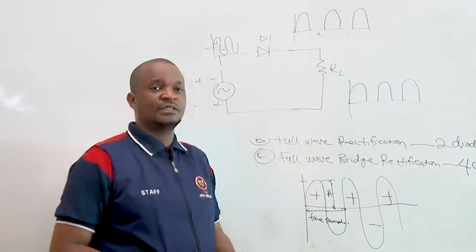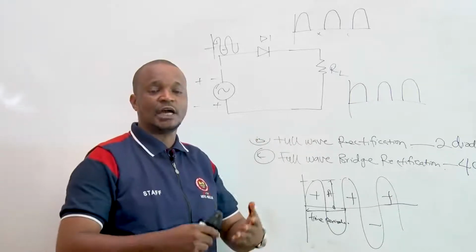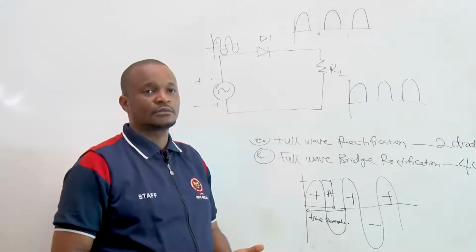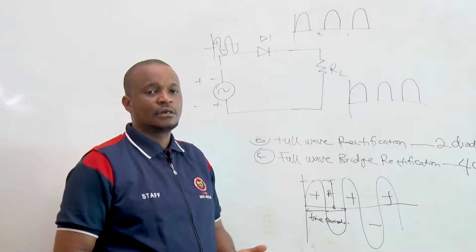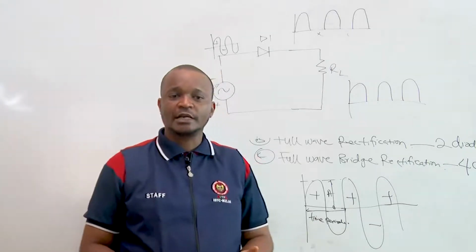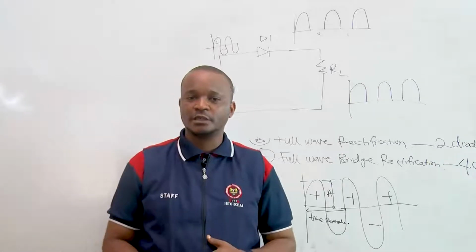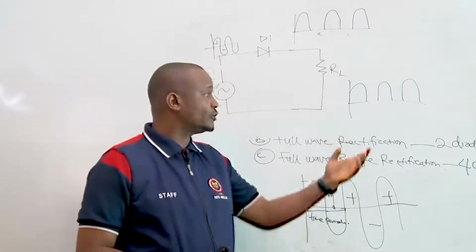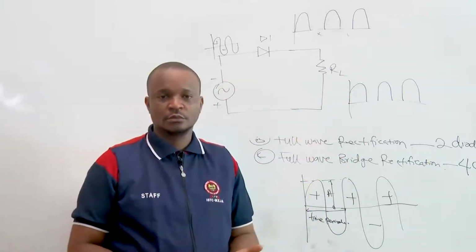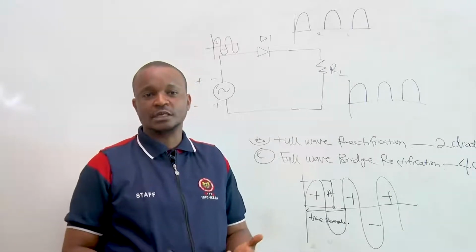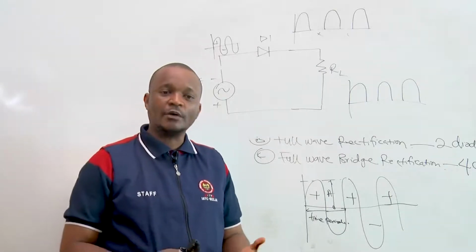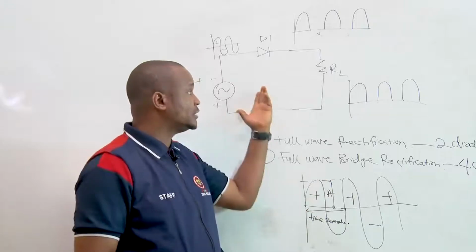However, there is a disadvantage to this. The disadvantage is that the output is difficult to filter. The output voltage can also diminish considerably when the power supply is connected to load. Also, it can put a disproportionate strain on the power transformers and on the diode.